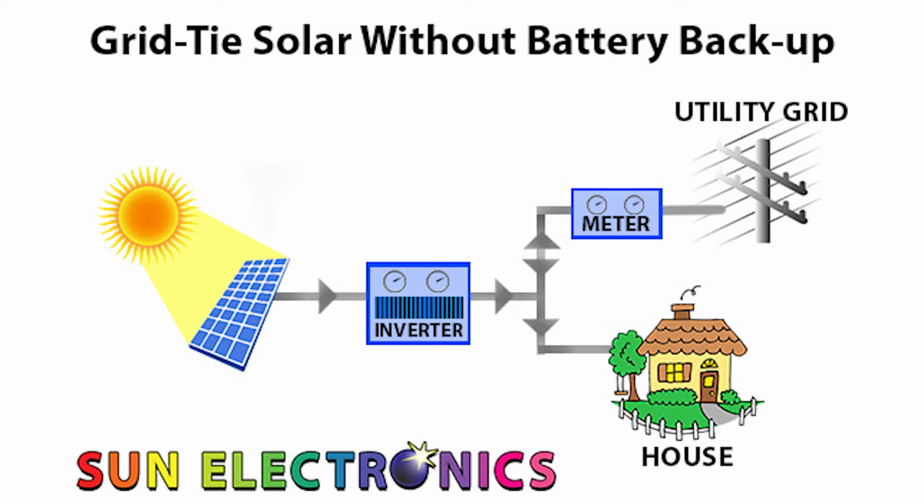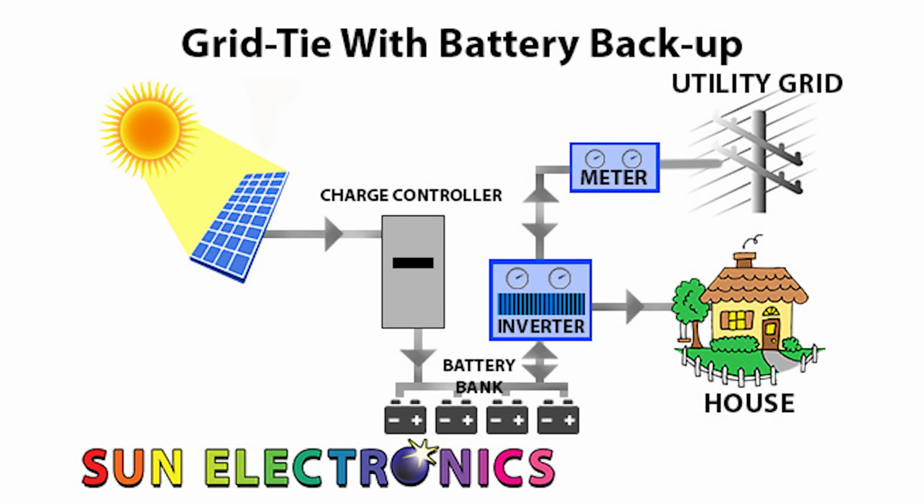Grid-tied systems work parallel with the utility grid. The DC power from the panels is converted into AC power so it can be used to power appliances and electronics. Installation also requires special meters that sell back excess power to the utility company. If for some reason your system produces less power than you need, you will receive power directly from the utility company.